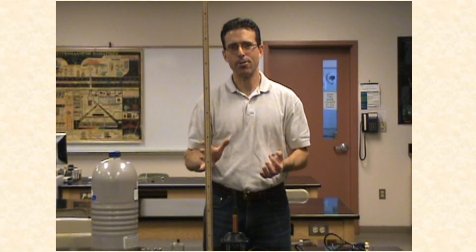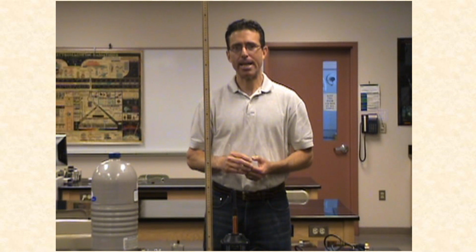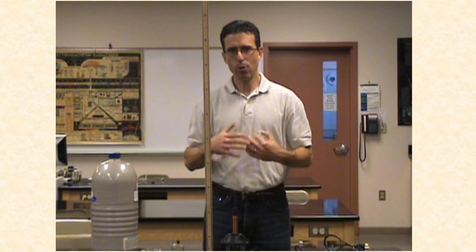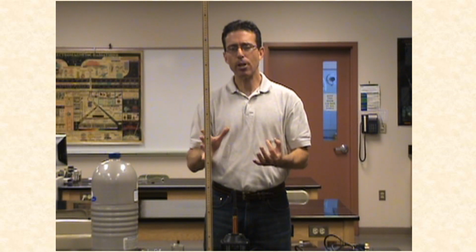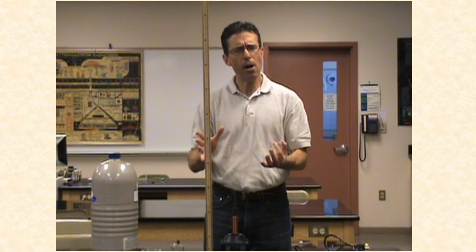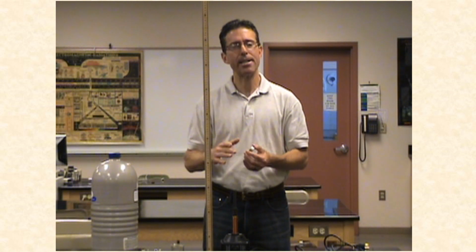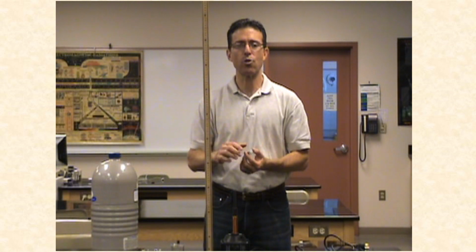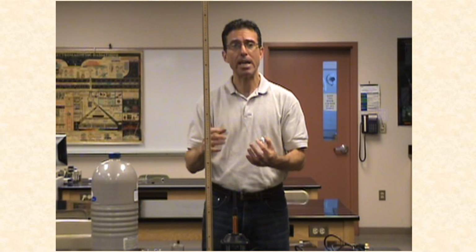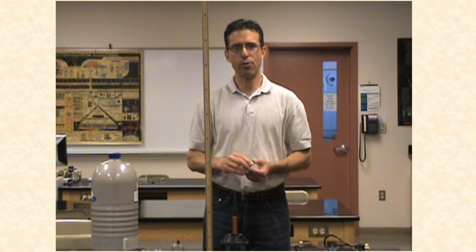Now, one of the factors that affects the electrical resistance is temperature. And it turns out that as the temperature of a material increases, so does the electrical resistance. If we look at this from a microscopic perspective, what causes electrical resistance in the first place is the motion of those metallic nuclei that are getting in the way of those electrons trying to move through the material. So it makes sense that as the temperature increases and we increase the kinetic energy of those nuclei, we're going to increase our electrical resistance.